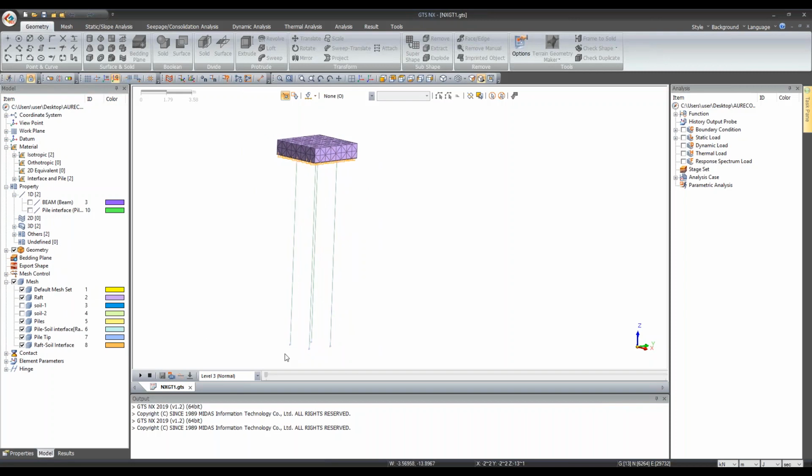I applied the pile tip at the bottom and even the pile itself as well, because if you go for a pile element, you will be finding a skin friction. If you're going for end bearing, you need to apply a pile tip basically.